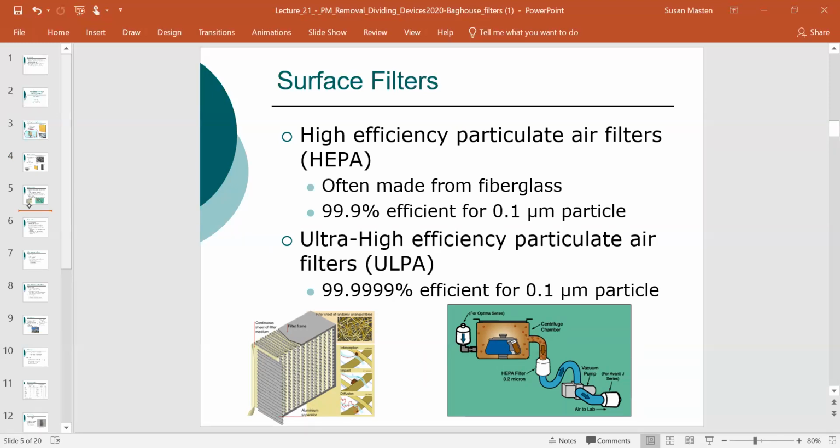They also have a much higher pressure drop across the filters, but they do remove, in this case, what we would refer to as 6-9 removal of a 0.1 micron size particle. These can also be used for removal of toxic particles, radioactive materials, and, as mentioned, microorganisms. In particular, you're looking here at removal of viruses, although bacteria would also be removed.